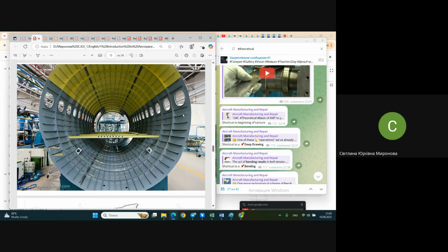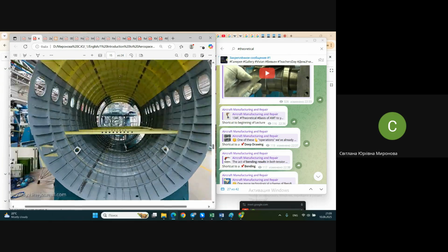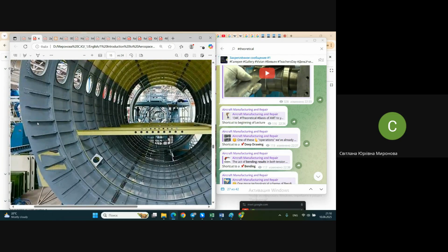That one, the outer side, the cylindrical fuselage, you already understand may be produced by roll bending, for instance. Stringers, depending on what they are made of, profiles or sheet. If they are made of profile, they already have a fixed cross section, and it's necessary only to cut the necessary length of the piece.